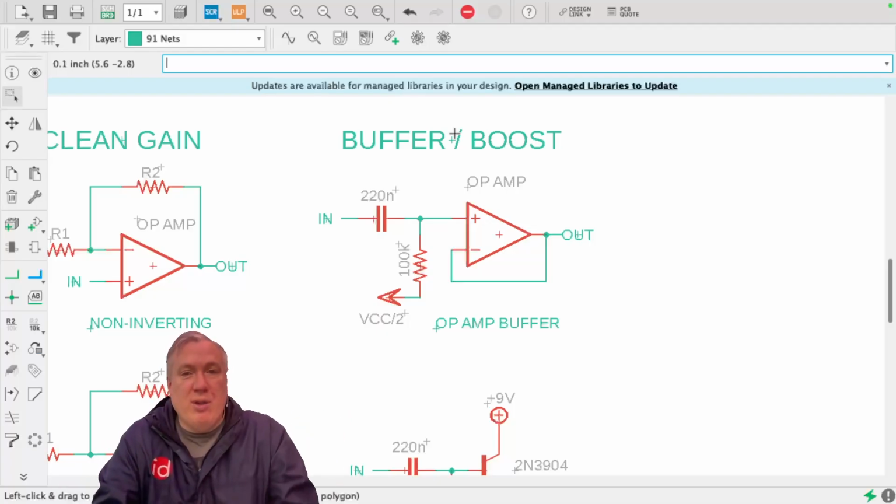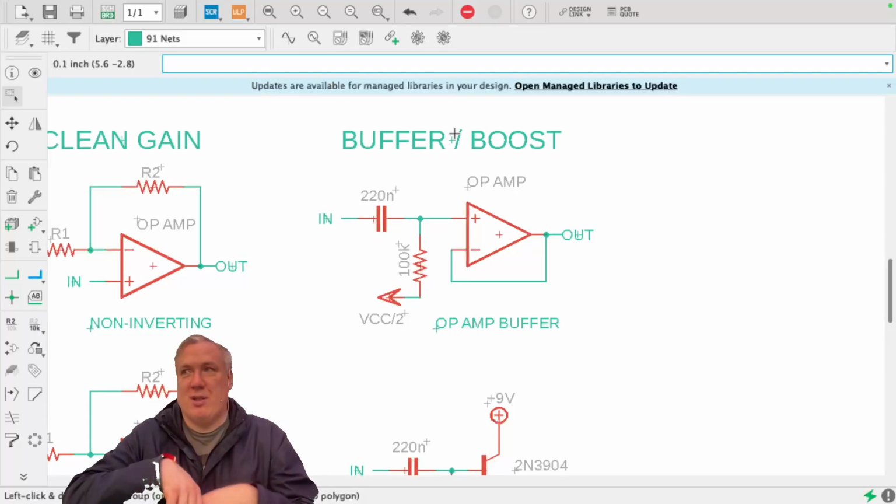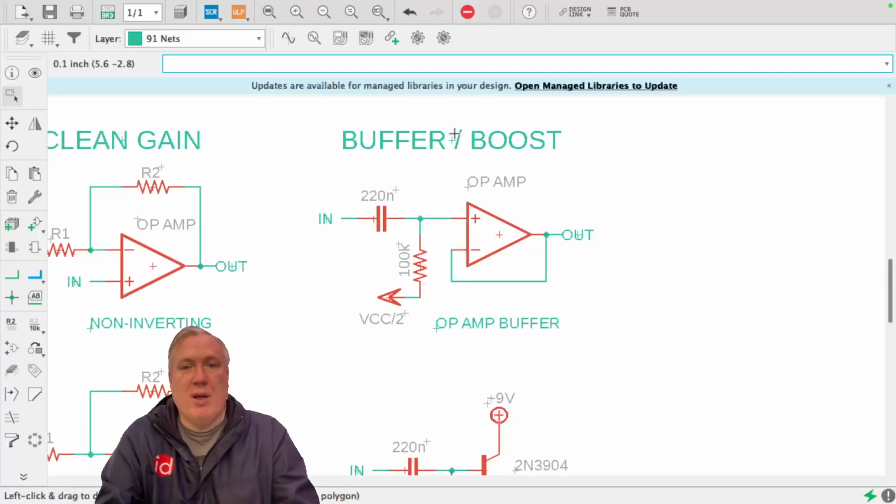So I'm going to coach you individually, but here's a generic one for the sake of the video. Can you guys pause your conversations? Thank you. For the sake of the video, I'm going to say this generically, but I want you to get coached individually. Generically speaking, if you have anything like a delay, reverb, modulation, anything like that, you're going to need a buffer just to split the dry signal out. Okay?